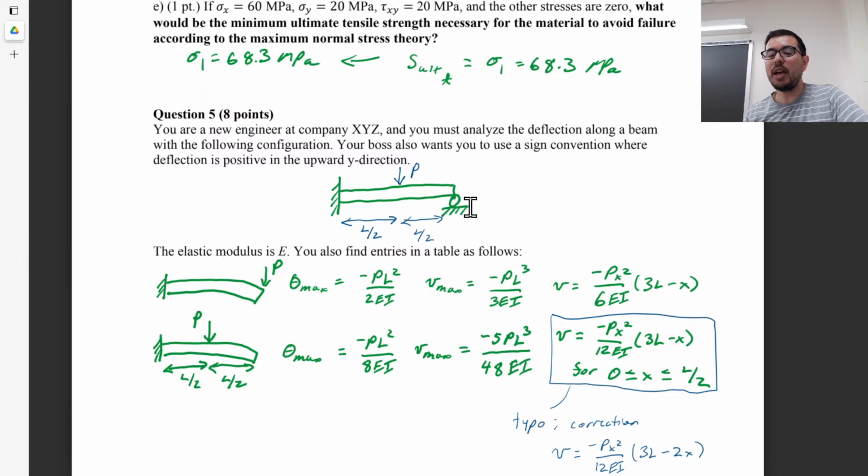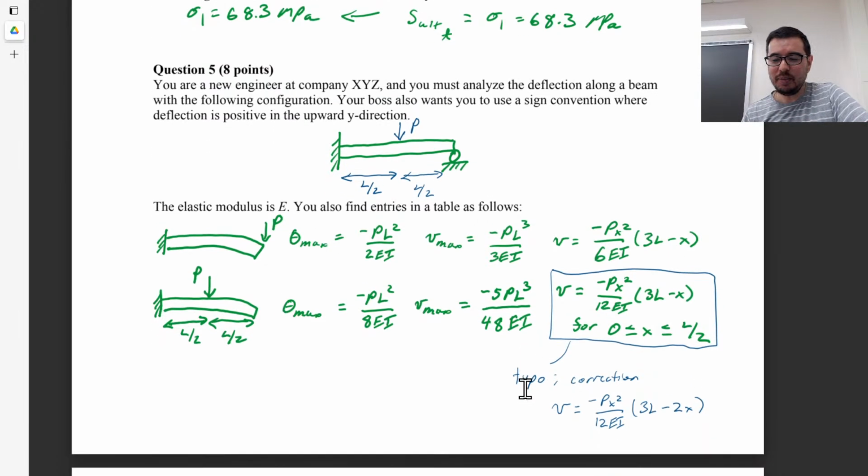Yeah, you see that? Because I could remove this support on the right and this wall would still be okay. Or I could make this a pin, right? So I could remove the constraint on moment over here, and that would also make it statically determinate. Yeah, if I remove one, I make it statically determinate. Currently, in this form, it's statically indeterminate. Okay.